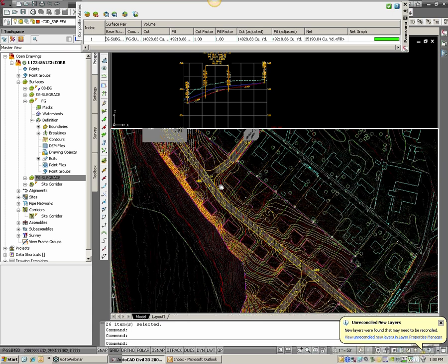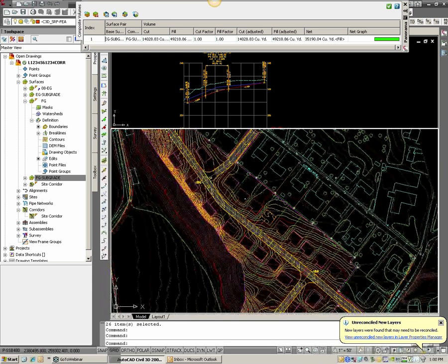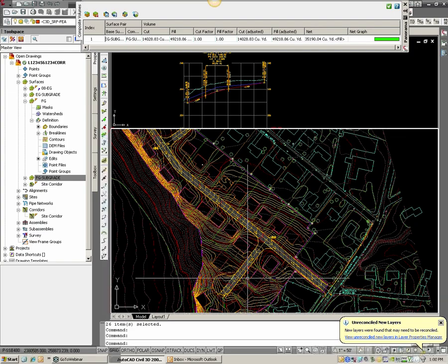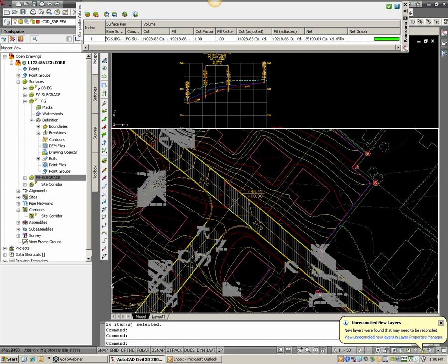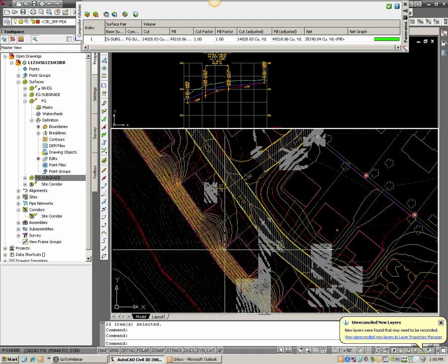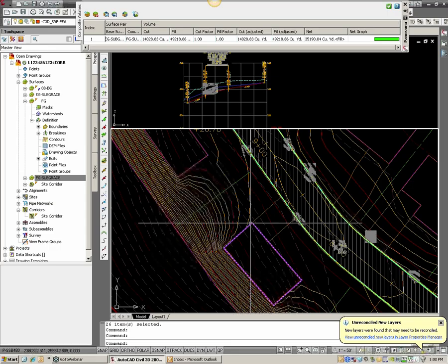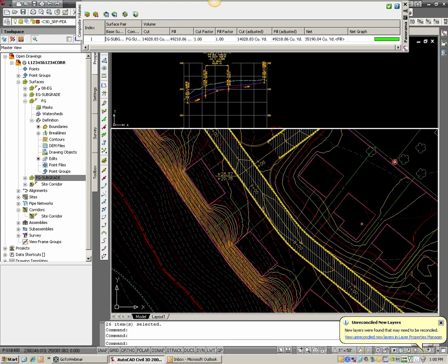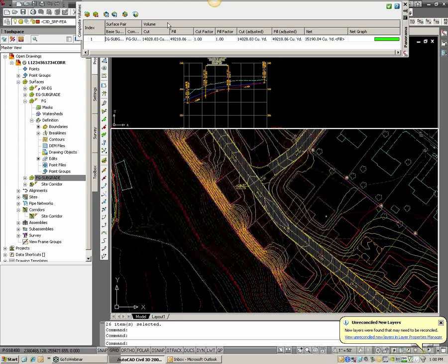And then once you are pretty satisfied with your earthwork volumes, you come through, design out these intersections for this one and this one. Tweak, this is just a first floor pad. So really this basement, this grade can come down as the house goes back, depending if you're on exposed basements or not. And as you're making these adjustments, keep this cut and fill volume up here, or bring it back up in the next session, next day, and re-hit that and see where you're at.